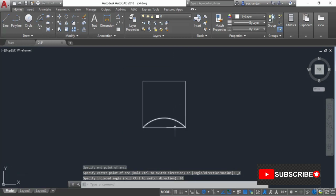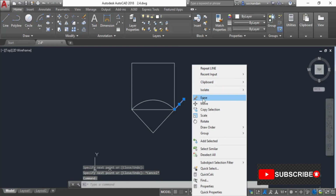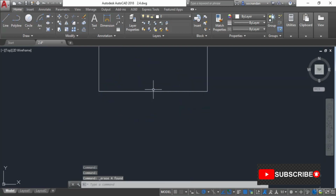Now you must be wondering what this 90 angle is. For explaining this, I'll make a line, and I'll click on this end point, and join it with the center point of the arc, and join it with the second end point of the arc. Now let's erase this extra line. So now the angle between this line and this line should be 90 degrees. And again, you can verify it with the same angle dimension, and we'll learn about these dimensioning later on. So here you can see the angle is 90 degrees. So let's erase these geometries and let's look at other options.